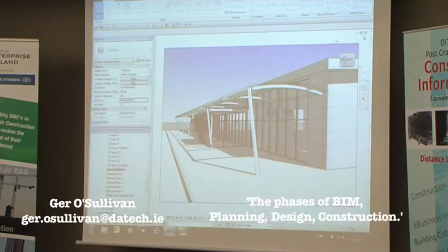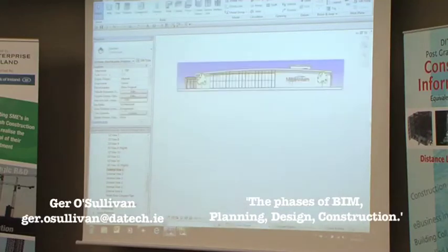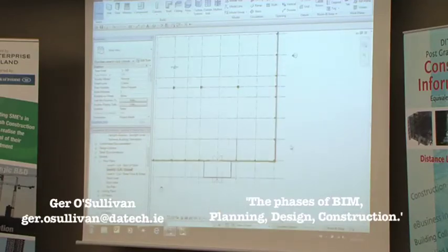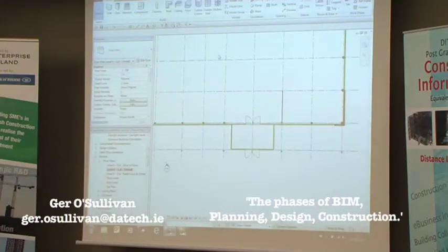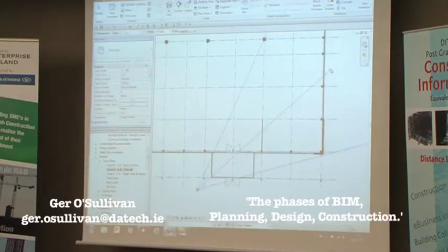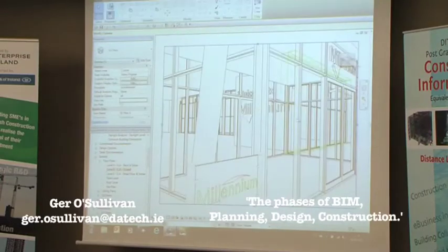So I just want to take you through the process of creating one of those for a presentation that you have to do. So let's go back into the plan view. And we'll just look at the front entrance here. Maybe we need to do a study on that. Go to our view and we'll create a very quick camera view. Okay? So I know I'm going fairly fast, but really we just need to get through a lot of this. So that's our camera view.